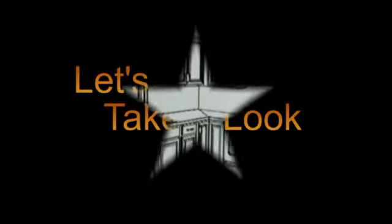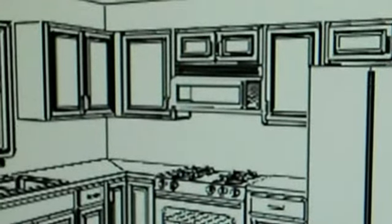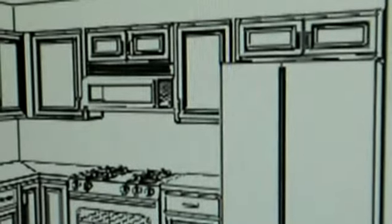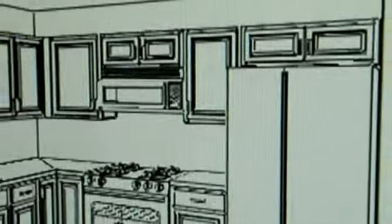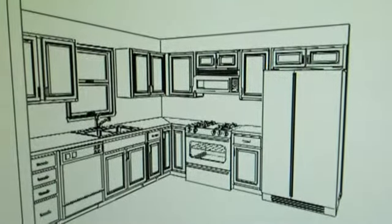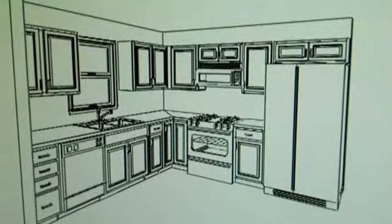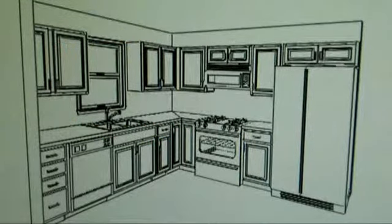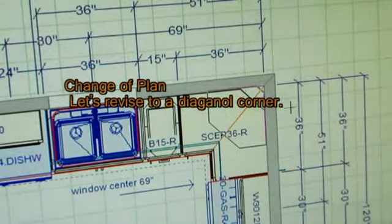I'm sure you noticed that I had an 18-inch to the right of the stove, and then the balance was that 36-inch refrigerator. See how clean that looks? The door above the fridge, door above the range, 12 inches tall. Also note how nice the microwave looks because it's up just a smidge above the cabinets next to it. And remember, we're maintaining 18 inches of counter space here, and our wall cabinets were set at 84 inches.